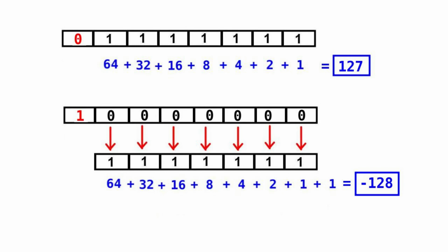But for this to work, you have to know ahead of time what type of data to expect, because some sensors will send unsigned values that are always intended to be interpreted as positive, and some will send signed values that might be positive or negative. So you have to check your device documentation and get your data types correct.